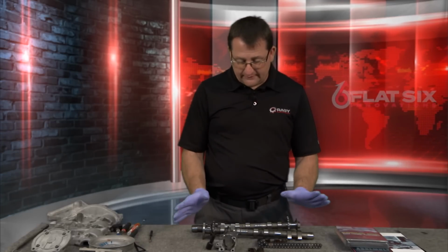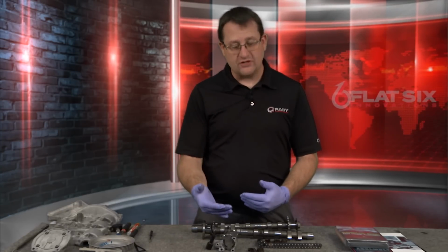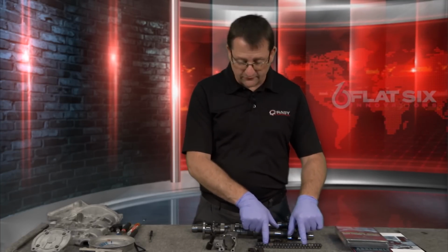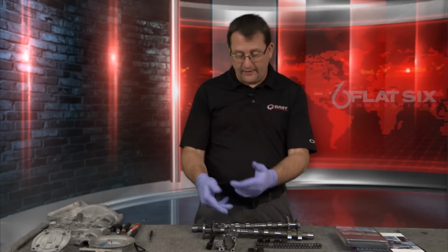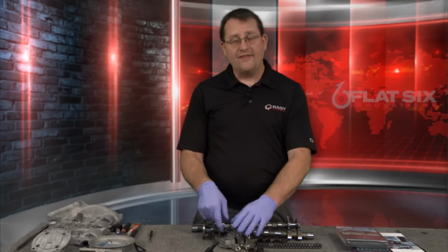So once everything's cleaned up, you're going to reassemble your camshafts. You're going to align the dots that you put on the camshafts with the discolored links that you've transferred the markings over to on your new chains. You're going to reassemble everything. You're going to back off this chain adjuster tool, and that's going to put tension back on the cams just enough so you can put them back in the engine.